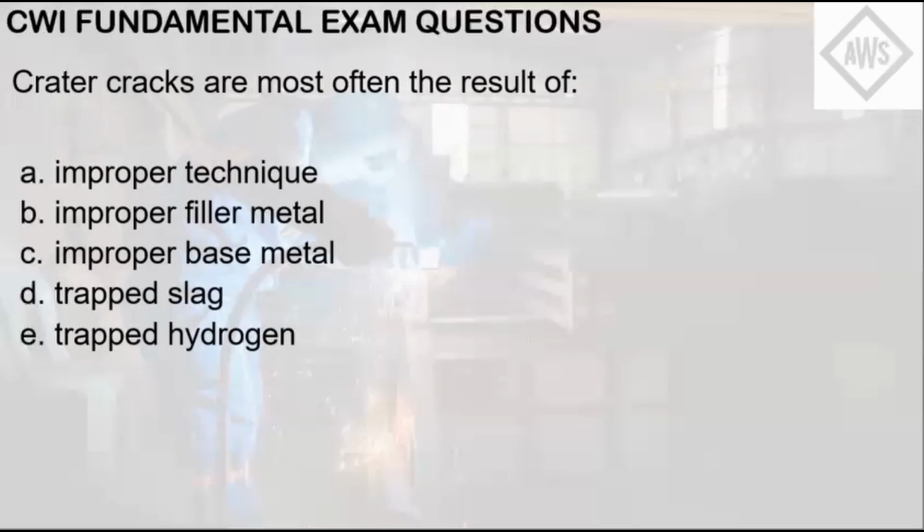So the crater cracks are mostly a result of the improper termination of the welding electrode in contact with the base metal, causing rapid cooling of that point or that area, causing shrinkage.